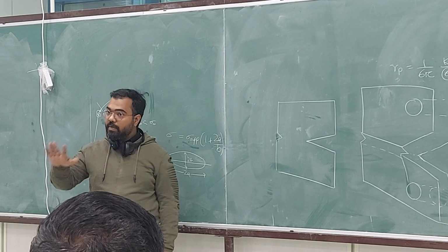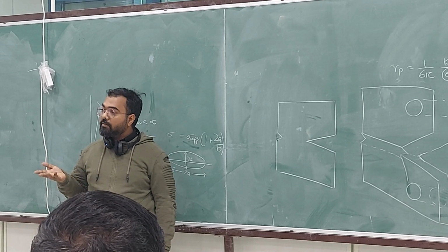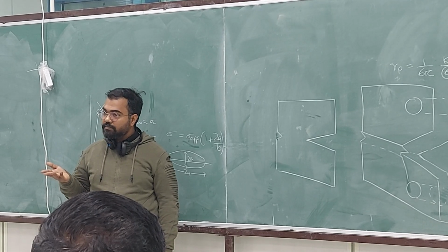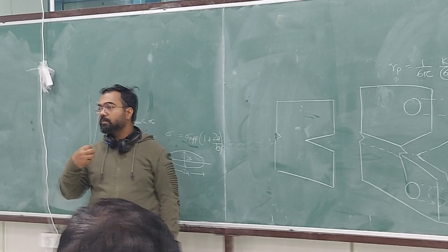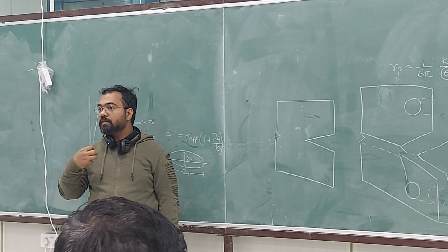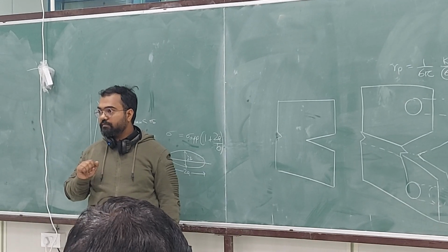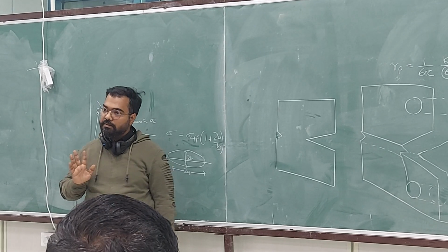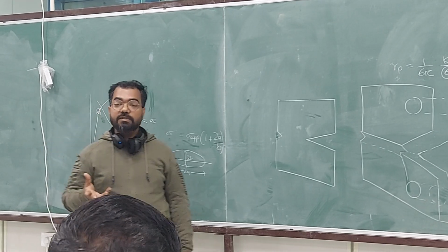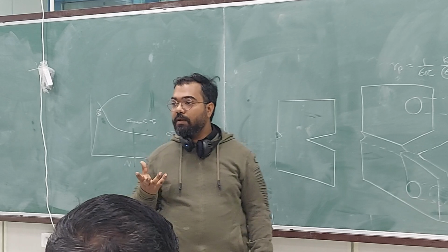Those slip lines were visible on the microstructure. It might have come because of polishing, right? So you do some heat treatment, or electrochemical etching or polishing, so that you don't enforce any strain on the surface. And then what happens?